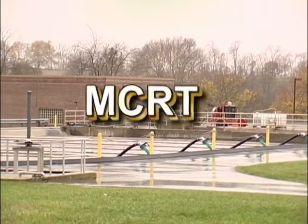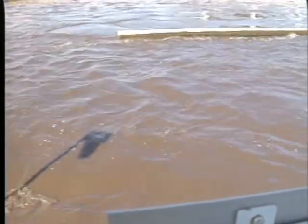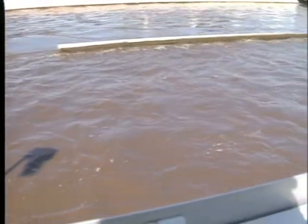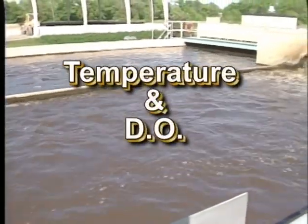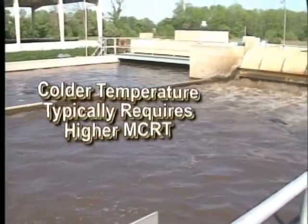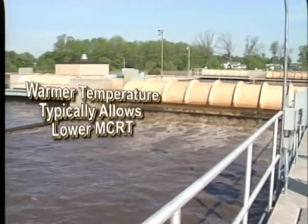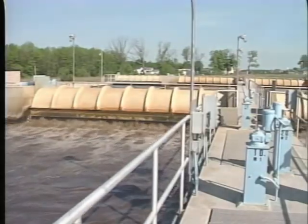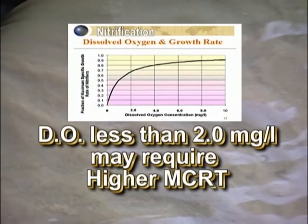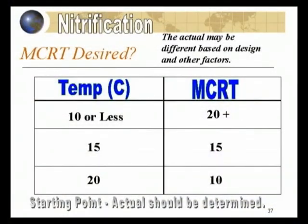Factor number 4, mean cell residence time. The actual required MCRT for nitrification depends upon the previous two factors, temperature and dissolved oxygen. During colder months, the MCRTs will need to be increased to achieve nitrification, while the increased activity during the summer months will allow for a lower MCRT. If the DO drops, the MCRTs will have to be increased to compensate as well. The following chart can be used as a rule of thumb.